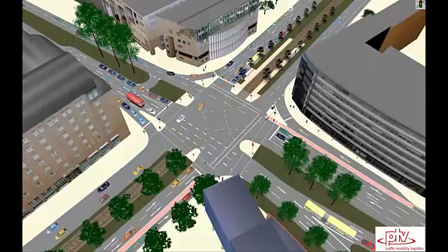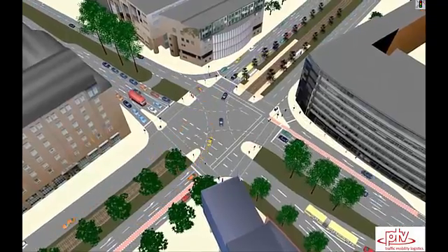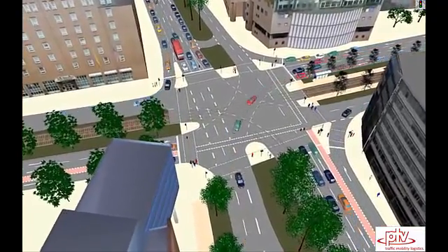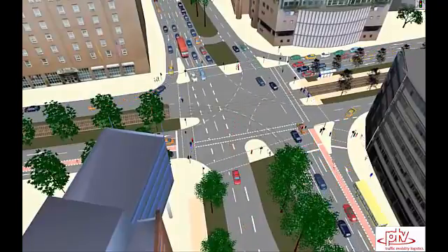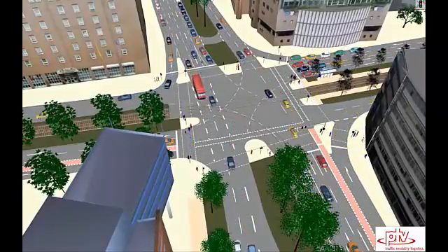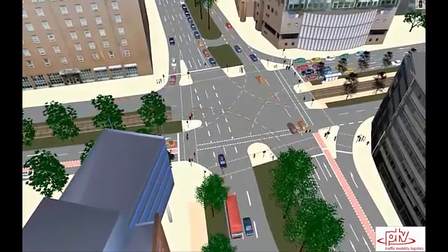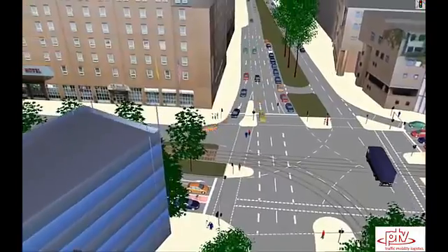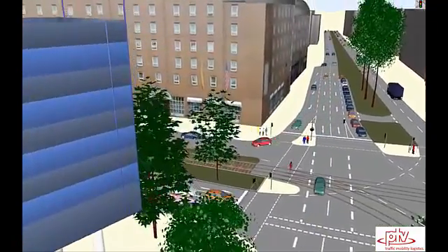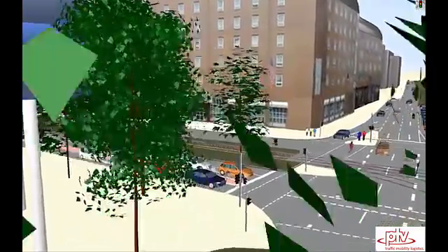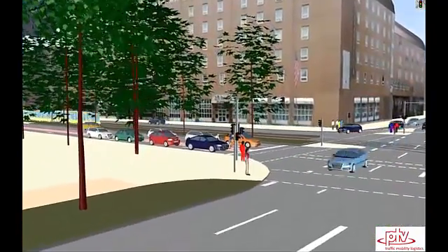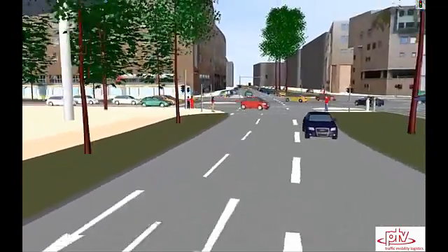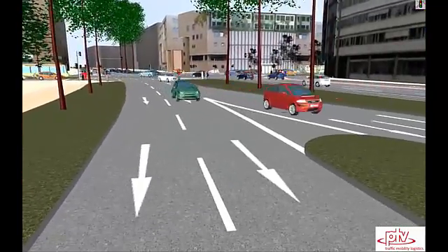The phasing, cabinet, detectors, and actuated controls all work together to produce a safe and efficient service at a signalized intersection. These intersections address highway operations for all users. They allow the shared use of road space by separating conflicting movements in time and allocating delay. However, in some cases, the dual objectives of mobility and safety conflict, and one element may need to be sacrificed to some degree to achieve improvements in the other. Overall, improvements in traffic continue to be one of the main objectives for transportation engineers.